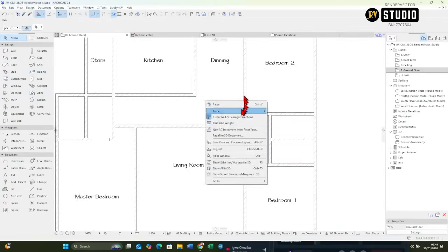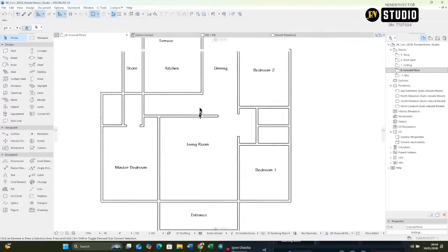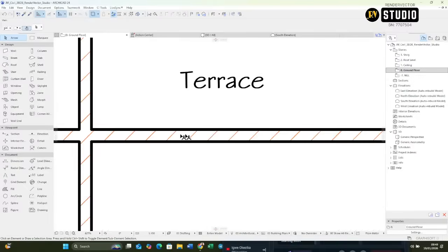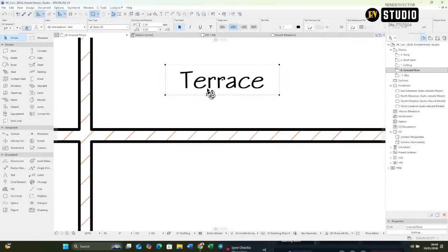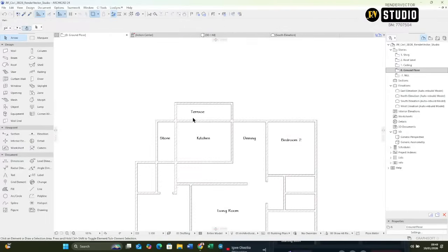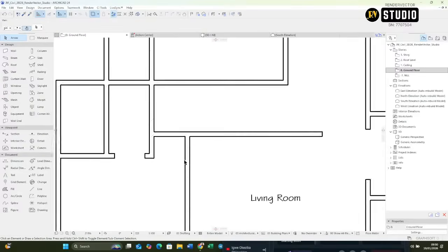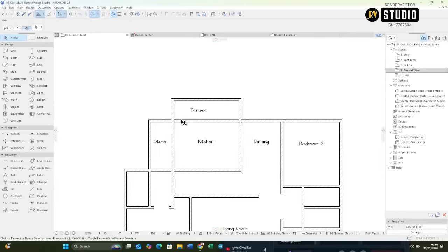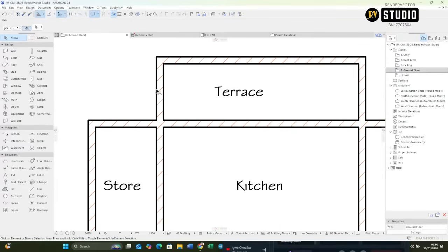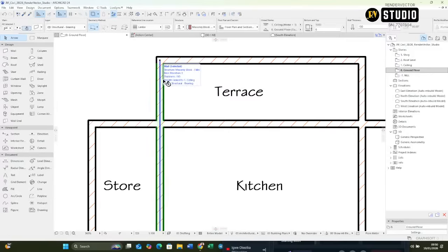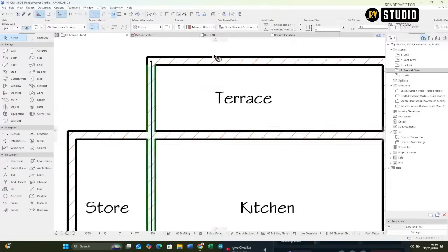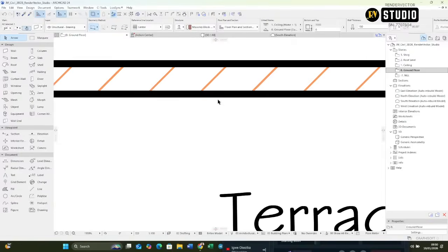You see how the floor plan is, checking through line width, share the floor. So now this wall settings, I need this dark wall to be thicker because it's kind of competing with this one here, you know, in terms of thickness, and there are other lines that are going to come and display based on the two-dimensional view. So the way I set my wall, I customize the thickness of my wall. So basically, if you check the wall settings, you're going to see that the cut line pen is the one. That cut line pen is this one and this one together.